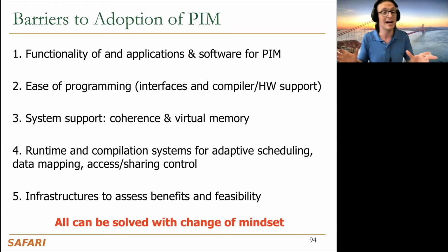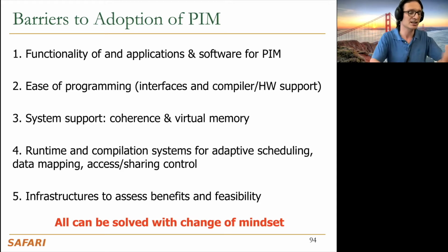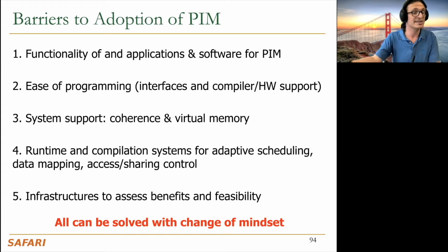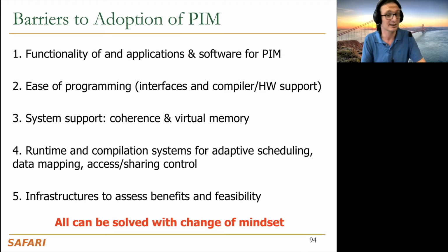Processor-centric designs actually violate almost all of them. Maybe critical path, you can argue, but certainly bread and butter. Common operations like memory accesses are handled terribly in a processor-centric system. That's the bread and butter design, optimized for the common case. Remember the microarchitecture design principles. Balanced system design principle is destroyed in a processor-centric system because the system is not balanced. Everything just stays idle or just serves the processor, and that's it, right?